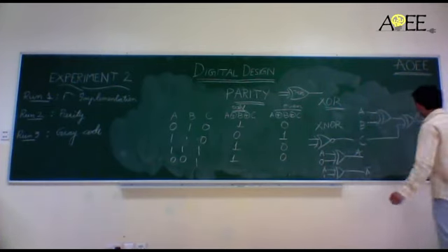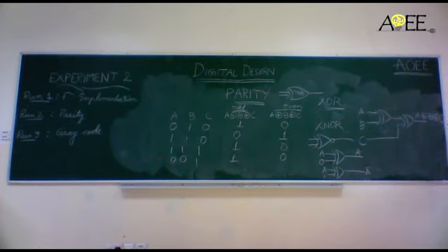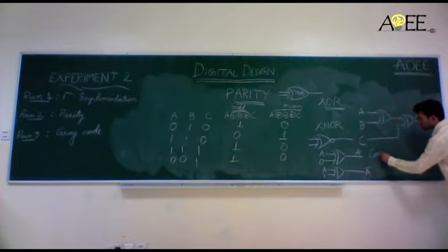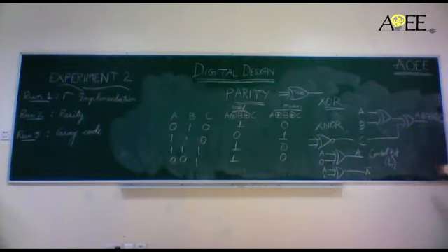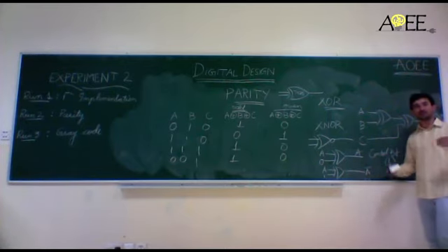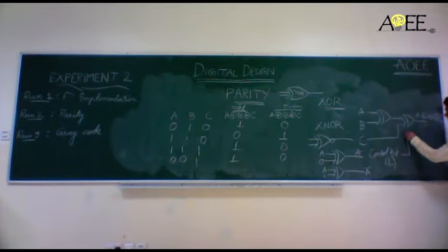So the idea is, here I have A XOR B XOR C. If this is treated with some external control bit, say L, or any other input which can be either VCC or ground, then we will have another XOR gate, and if this is 1, then the output will be A XOR B XOR C bar, or in general, a single bar.